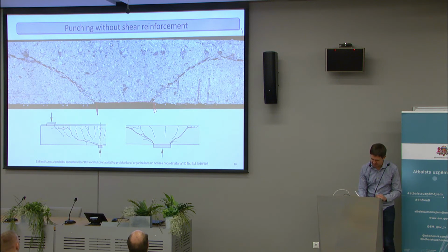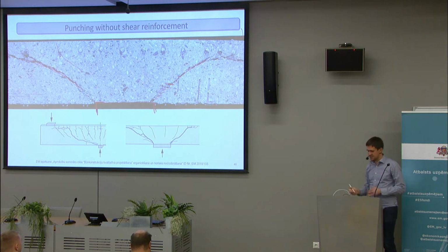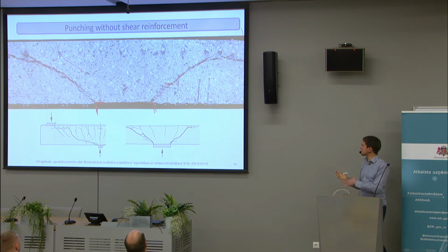Outside we only saw that this plate in here has punched a bit inside the slab, but when we cut it, we see that this is why it failed. This is because there was a flat crack. You can see some of the remains of the flexural cracks in here as well. You can probably also distinguish the compression zone, where the concrete looks more crushed, and that's the tension zone, or the neutral line is somewhere in here. So here the concrete is not as much crushed, but the crack edges are a bit cleaner.